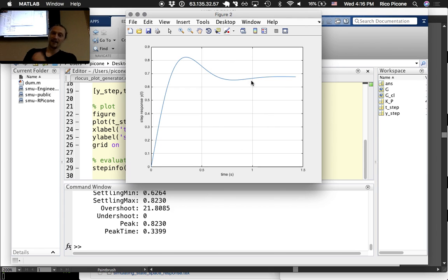However, it needs some integral in there, right? It's just a proportional controller that gives us the settling time we want, but it still doesn't go to our final value, even close really. So we need to improve that, which we would do by adding an integrator.